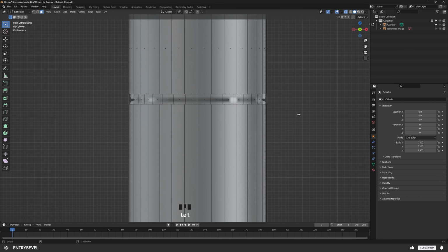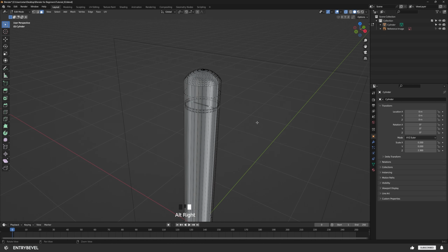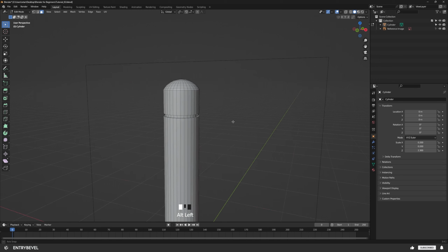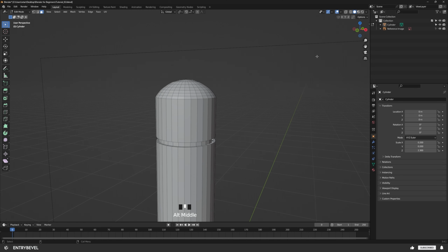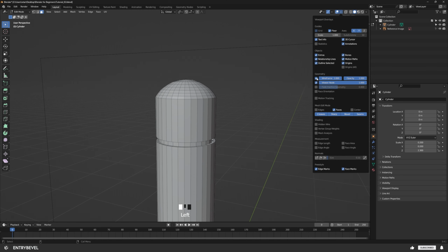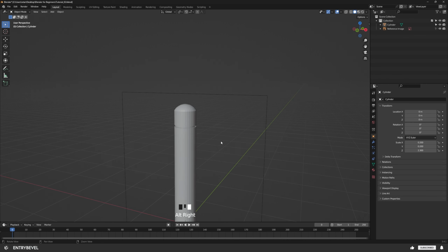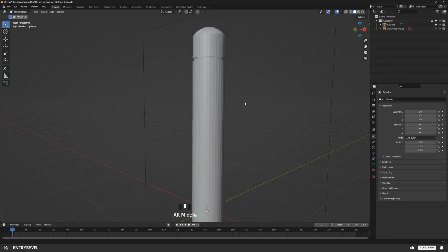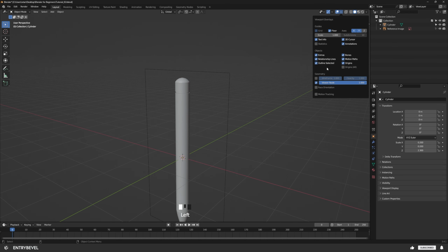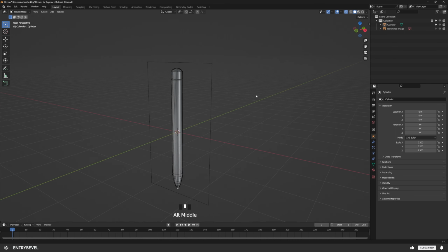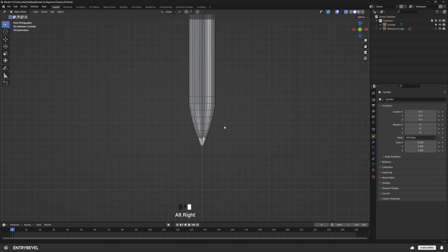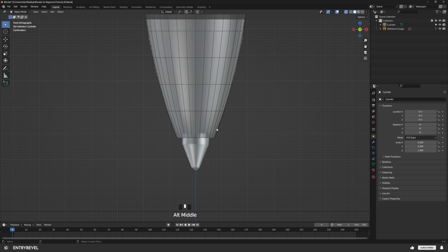And click on it and check it out in our perspective. Let's turn off X-ray and see what it looks like. Nice. We have a nice big gap. Turn off wireframe and go to object mode. Nice. We have our gap. All right. Let's turn these things back on again. X-ray. Back to front. Now, we're going to use inset.